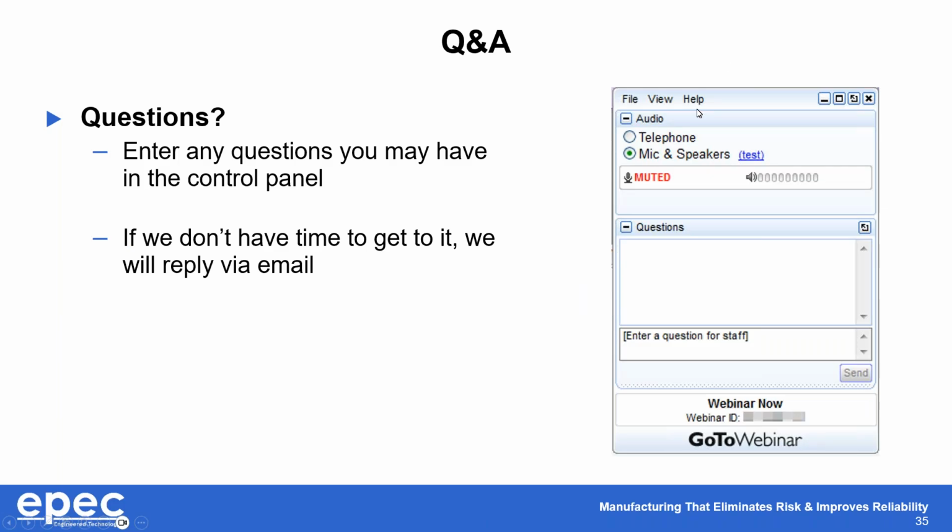First question we have here says, what's the highest wattage heater you can make? So I know the size limitation is what's going to be the issue here, and it's more the watt density. But the reality is, if you're comfortable with a silicone heater with a wire wound heating element, we can make this almost infinitely large. That's not entirely correct, right? But the truth is, as long as our watt density is below 10 or 20 watts per square inch, and that you can provide enough voltage to drive the heater, we can make it as long as you need.